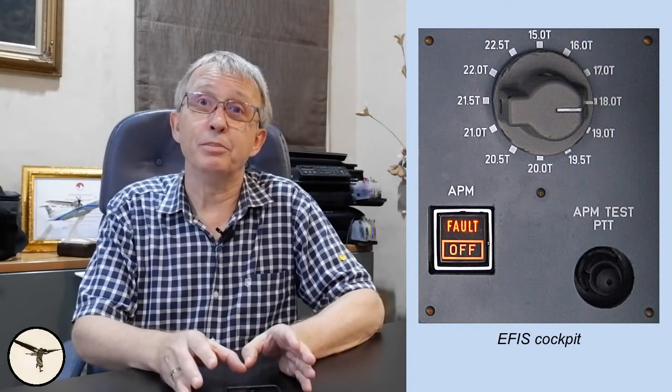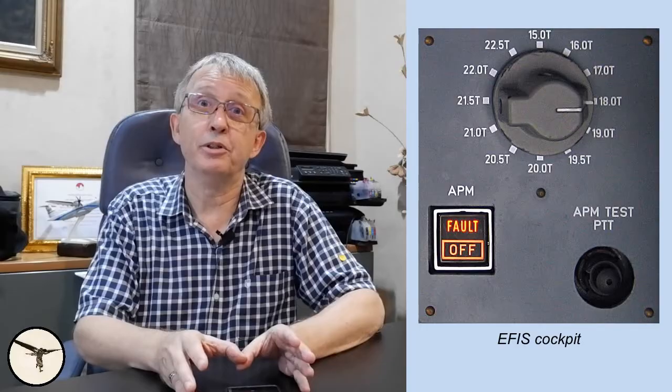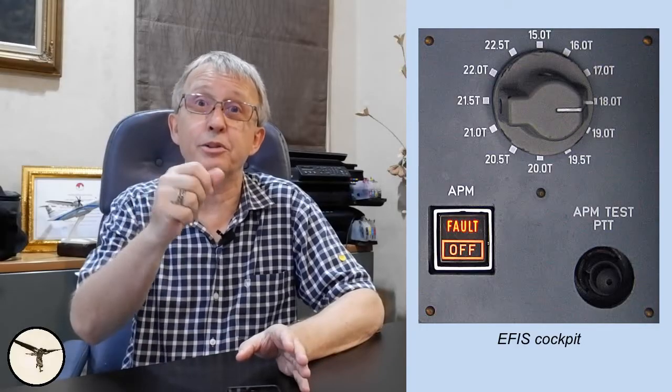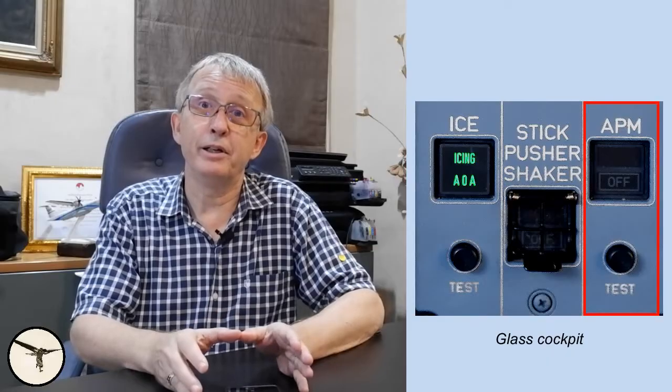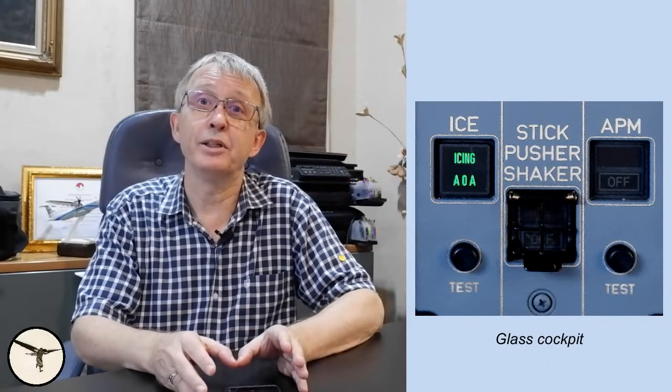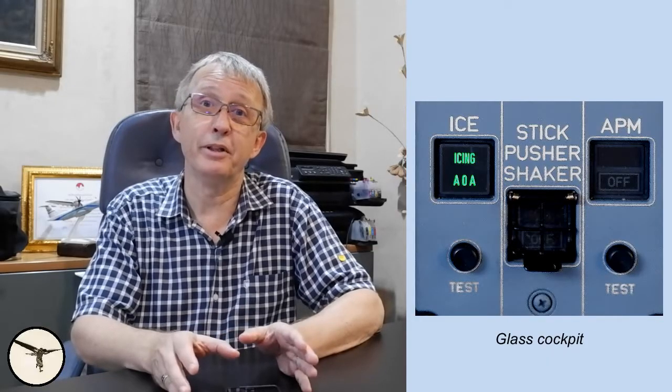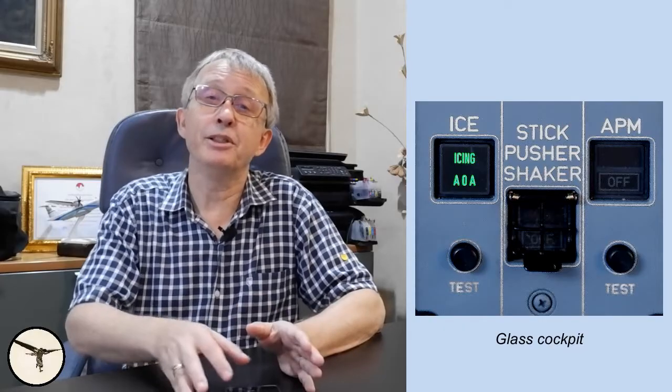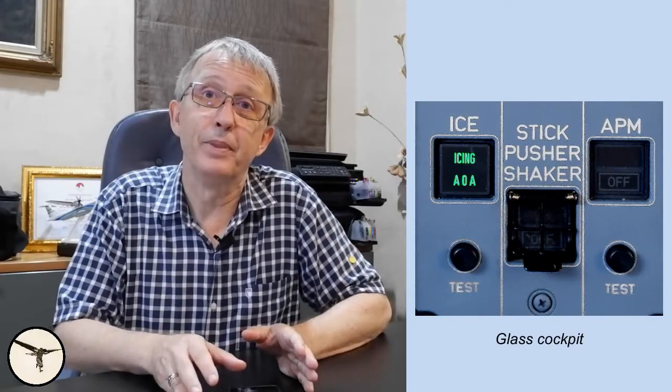Because the fuel consumption is subtracted from the weight you set before the previous takeoff, it is important that you, before the next takeoff, turn the knob at least one notch in order to set the new takeoff weight. On ATR 600 variants, the control panel has an on-off push button and a test button only. The weight information is provided by the FMS.